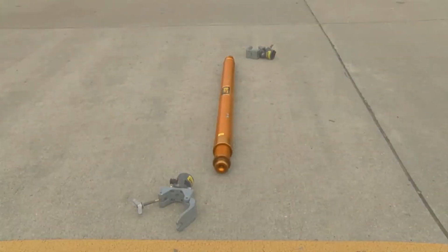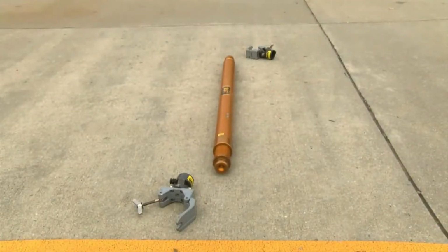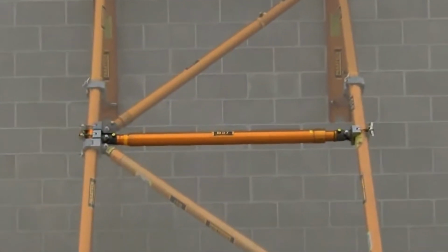A B57, which is a brace, and 2 clamp and clevises. Attach the clamps and clevises on both ends of the B57 and extend the brace out so the center of the clamps and clevises are at 72 inches or 6 feet. That means when they attach the lateral bracing to the raker assembly, it will fit perfectly.